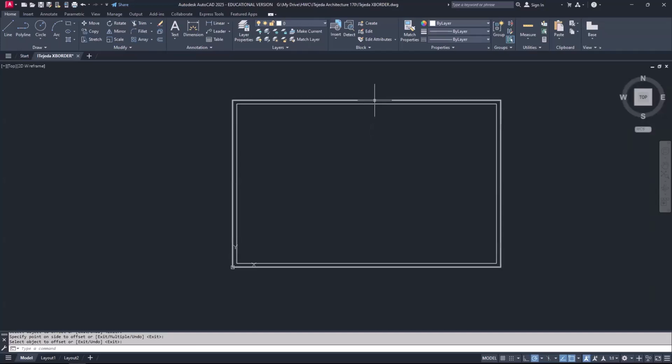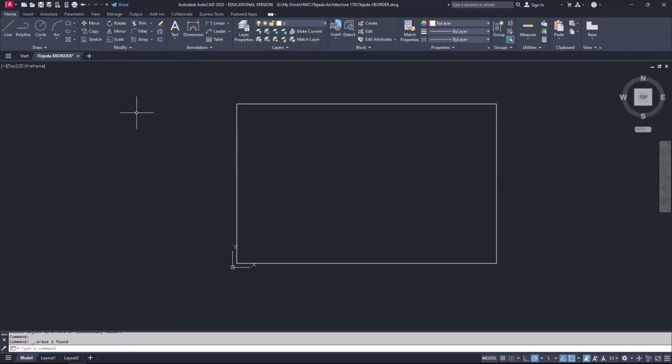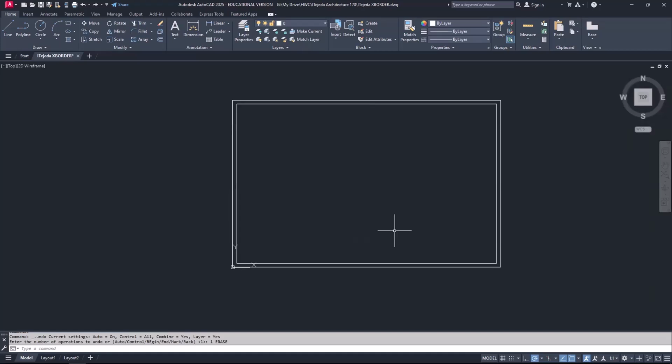And I'll select this outer rectangle and delete it because I don't need to see that sheet size. Unless, and let me do this, unless you want to leave it there for now, just as a guide. I'll show you a little later what we can do with this, if you'd like to keep it just for reference. So I'll go back to my quick measure and I look in here, and yes, it is now 1'4.5" by 10.5. So great. Let me tap the escape key.